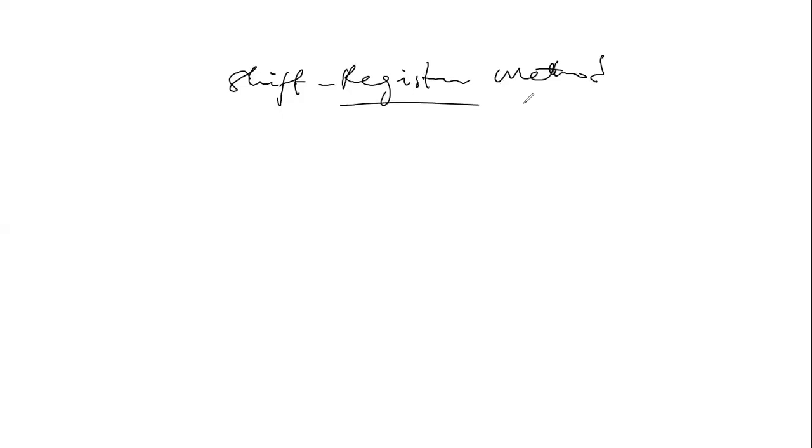If we consider an (n,k) convolution code, for instance, let's just imagine a 2 by 1, where n is 2, k is 1. Here we can tell the rate, which is k over n, which is 1 over 2, okay? So we have a half rate convolution code here.